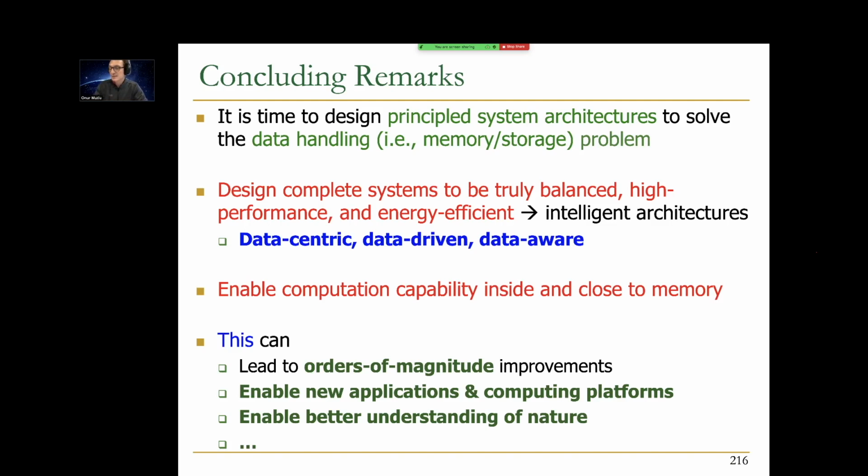Their architecture has a lot of limitations also. I think the lack of communication, for example, between different processing units inside the DRAM is a problem in terms of enabling more applications, meaning being more general purpose, as you mentioned. And general purpose at some point is very, very interesting. So I think we need to overcome some of those. Some of those are not going to be so easy to overcome with the technology that we have. Like the DRAM process is not very good at adding a lot of interconnects inside the DRAM chip itself. With 3D stacking, I think we can overcome some of those. So I believe 3D stacking can alleviate some of these concerns, even though it may not get as much benefit as inside the DRAM computing.